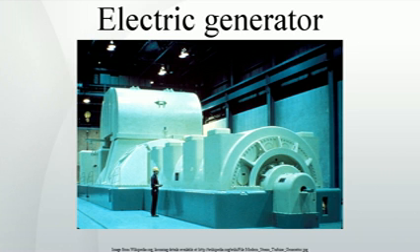Electrostatic generators operate by using manual, or other, power to transform mechanical work into electric energy. Electrostatic generators develop electrostatic charges of opposite signs rendered to two conductors, using only electric forces, and work by using moving plates, drums, or belts to carry electric charge to a high-potential electrode. The charge is generated by one of two methods, either the triboelectric effect, friction, or electrostatic induction.